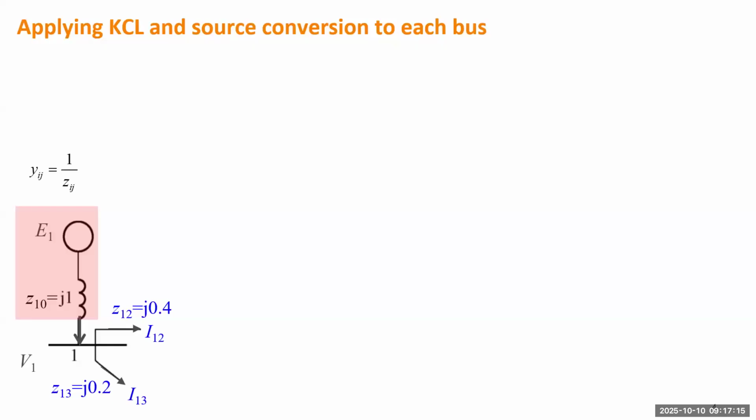Just think about if you want to solve power flow for, let's say, the eastern connection of the entire North American system. Even if you only study voltage levels above 100 kV, the model has something like 100,000 buses, probably 100 to 200,000 branches. Are you going to apply Kirchhoff's current law and voltage law to each individual bus or branch, then try to solve the power flow? Theoretically speaking, that's a solution, but it's not very practical.